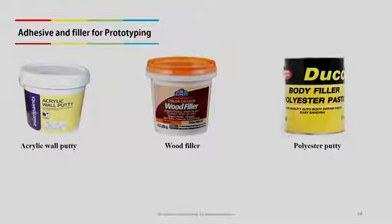Any kind of dent or any kind of corner you have to fill with materials with the filler. So, in the list of filler material we have acrylic wall putty, which we can use on top of thermocol, we can use it on top of PU also. Next is wood filler. We can use wood filler on top of MDF, plywood and wood, and next is polyester putty.